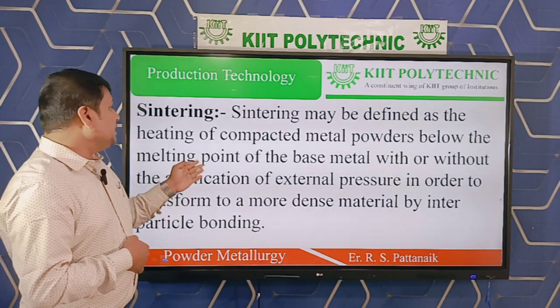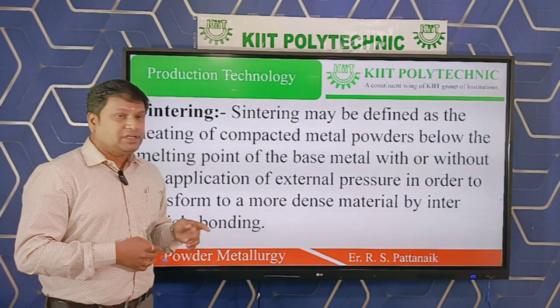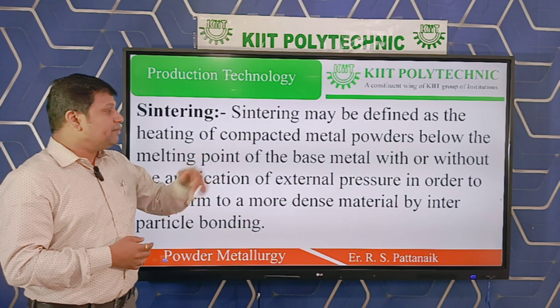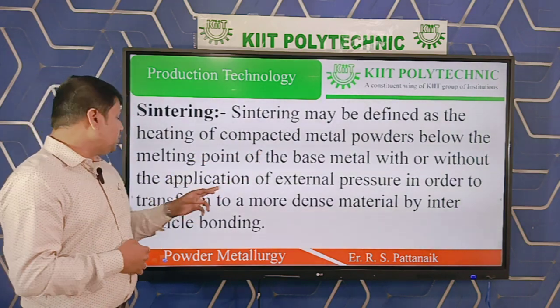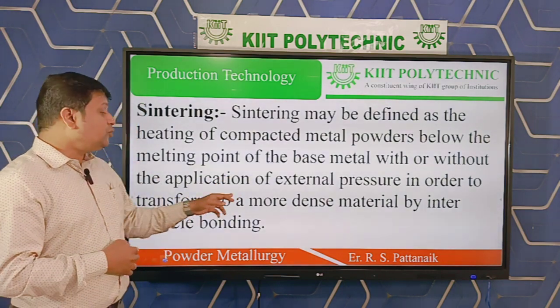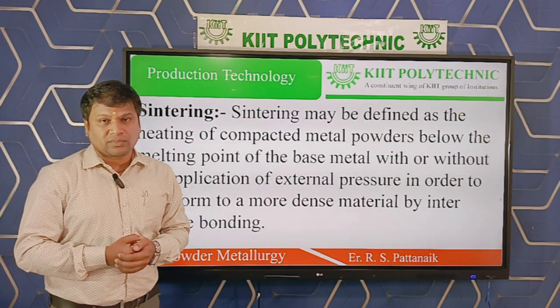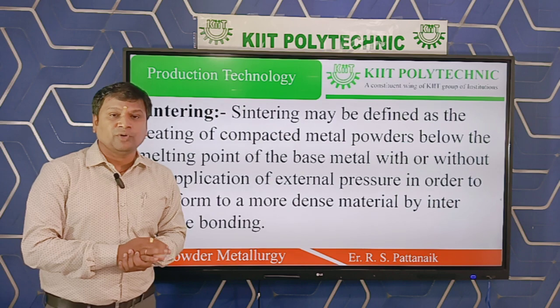Okay, so sintering may be defined as heating of compacted metal powders. As I said, sintering may be defined as the heating of compacted metal powders below the melting point of the base metal, with or without the application of external pressure, in order to transform to a more dense material by interparticle bonding. Very important step. This is sintering from exam point of view.